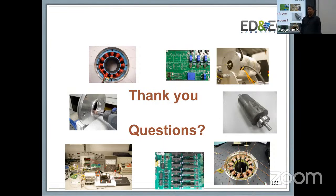Yes, that method has also been done for a 3-phase machine. There are papers that have shown it's possible to continue operation reasonably okay with a phase winding out, but more often than not, you would see that question being solved by going to a higher number of phases. That way, even if one goes out, you still have 4 phases left.